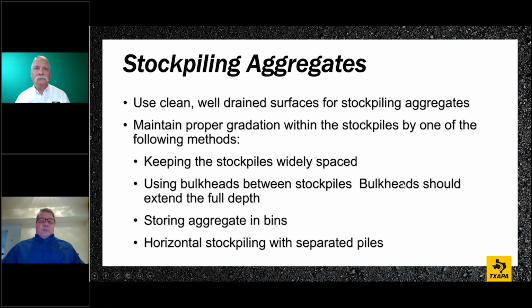We need to use clean, well-drained surfaces for stockpiling aggregates. Maintain proper gradation with stockpiles by, again, keeping the stockpiles apart. We don't want contamination between stockpiles. Use a bulkhead between stockpiles, and the bulkhead should extend the full length of that stockpile. If you don't have a good footprint to separate them, you need to put a bulkhead or something to separate them. And then storing aggregates in bins, that's another method of utilizing good practices at your stockpiling of your aggregates.